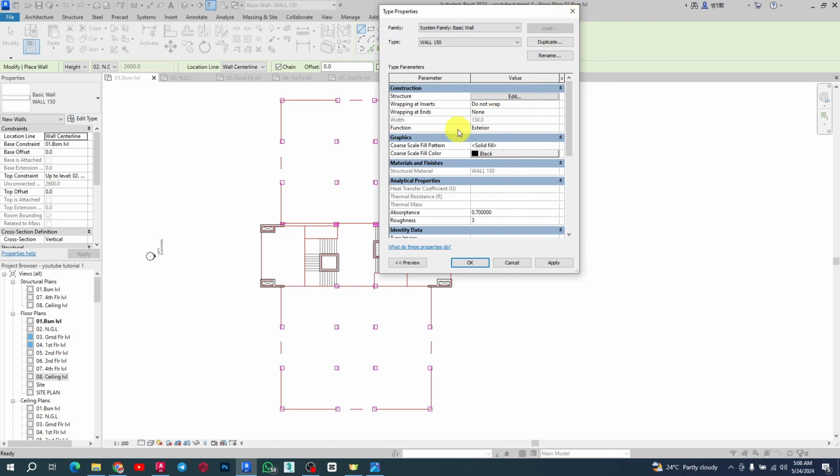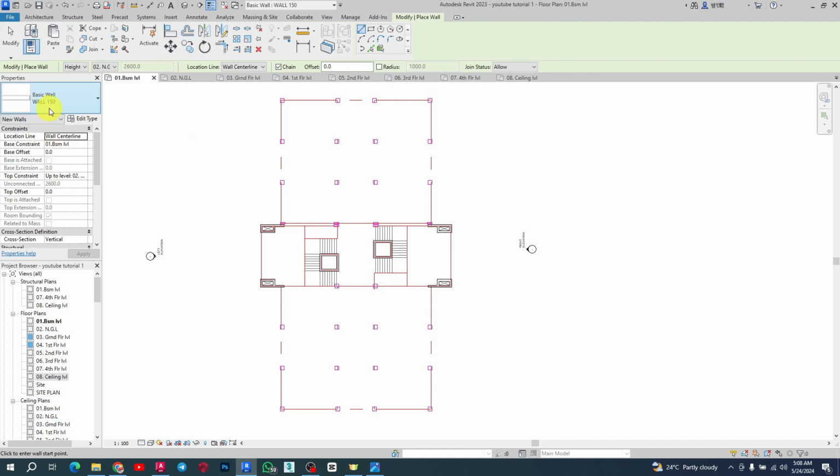Whatever you change on that particular wall, like editing the structure, is going to change that family for you. That family is going to be updated, right? The wall thickness will no longer be 150. So it means that you always get to be changing them. So the very good practice, if you have a particular startup, like basic wall, for instance, or an object that you want to put in your model, and you don't want to affect the mother object, right?